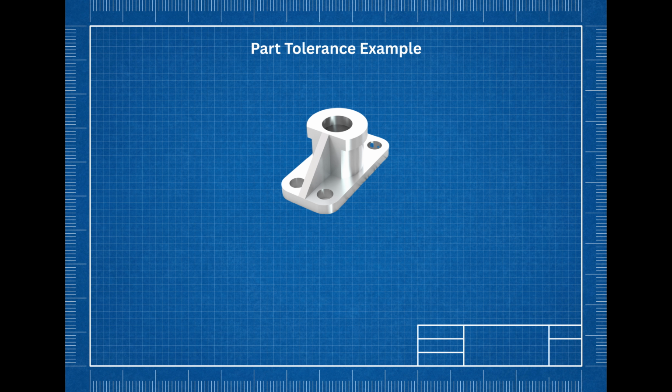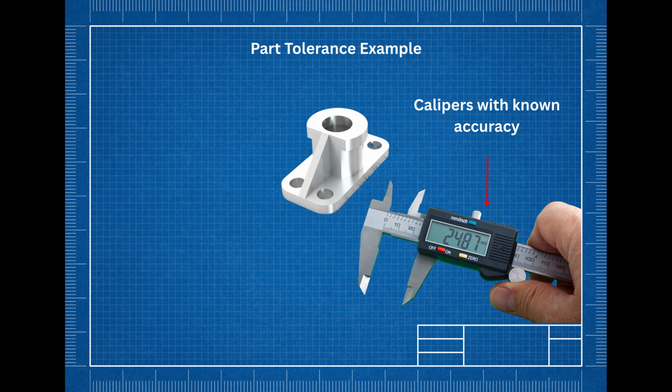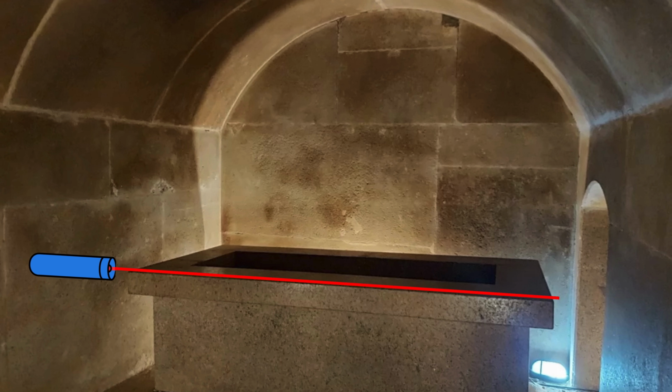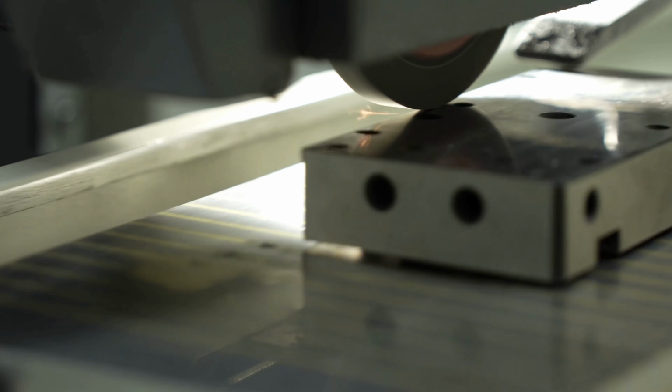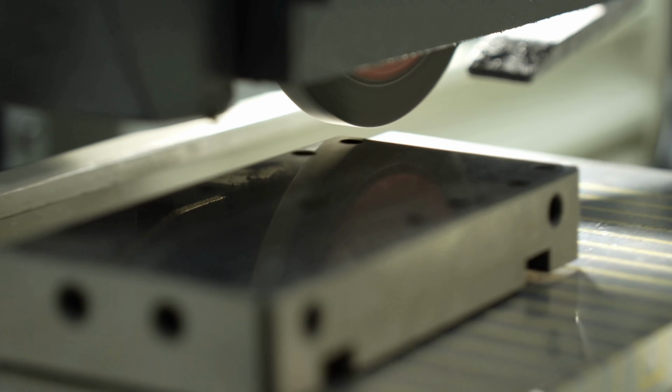To measure a tolerance, or to have one, you need a numerical reference, the nominal geometry, and a measurement method that produces a quantitative deviation from that value in inches or millimeters. And you have to have a known instrument accuracy. A laser line alone gives you none of those. You're just eyeballing coincidence between those two visible edges, with no way to read out the deviation. Remember, the process of machining something flatter and flatter through those various stages is logarithmic.